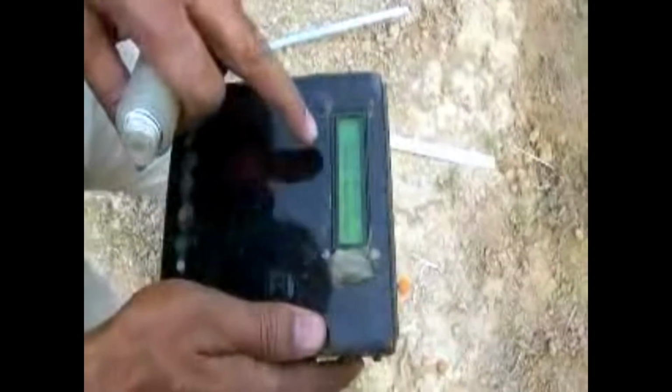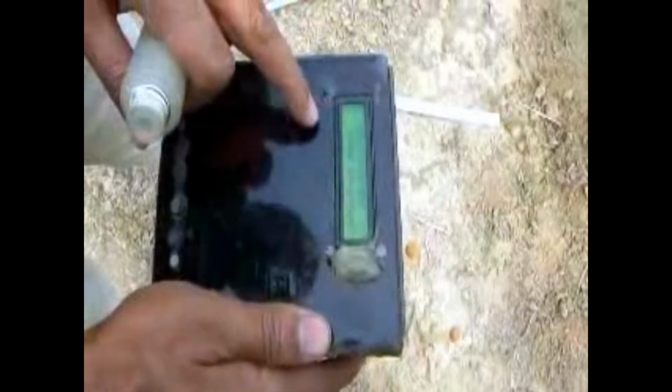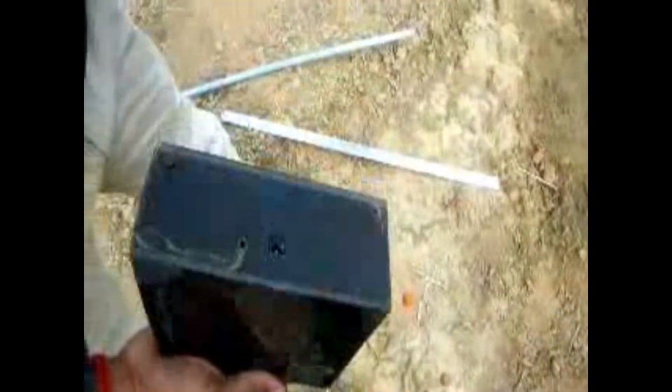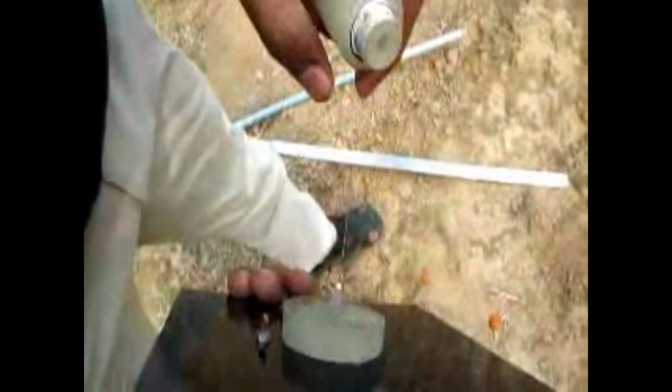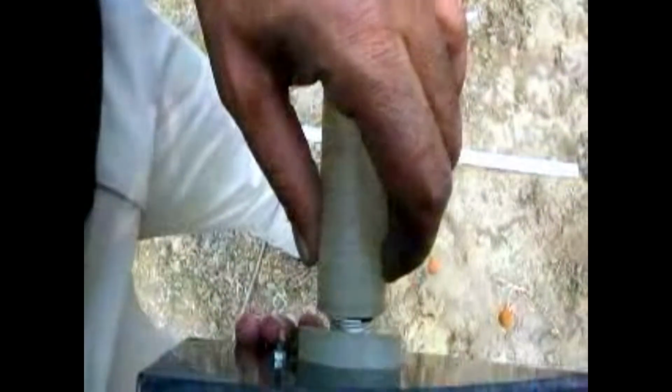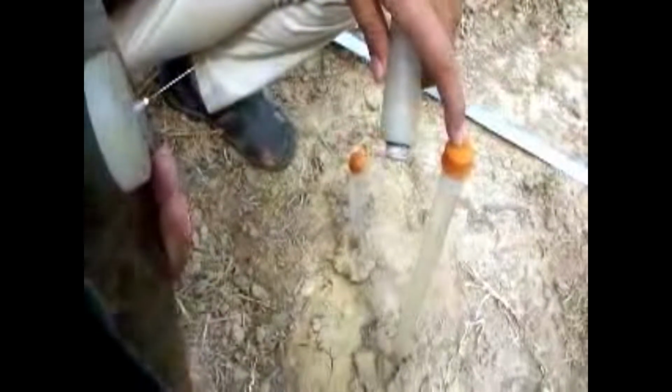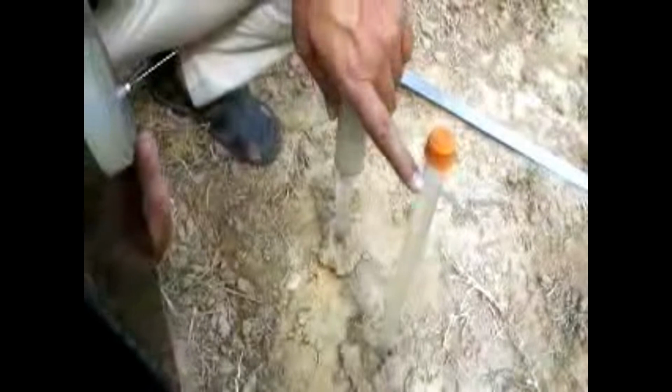We have a device to read the tension or suction pressure created inside the tensiometer because of the hydraulic head or suction of the soil. This readout unit has an opening with a guide. We put it on a special rubber cap, which can be punctured by an injection syringe about 100 times and still does not allow air to get inside the tensiometer tube.